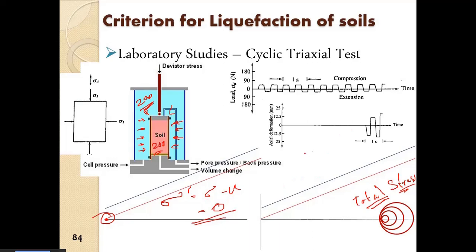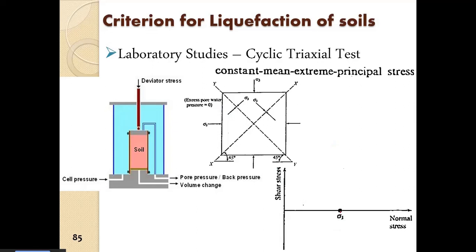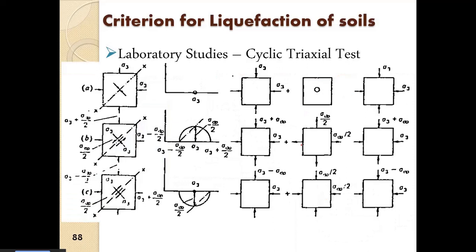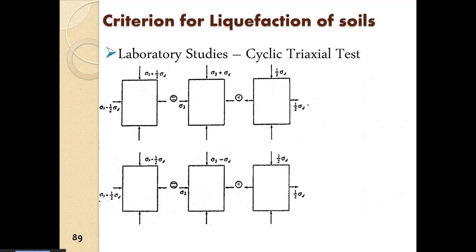So this is the liquefaction simulation in the laboratory, using the triaxial test. This is the cyclic triaxial test. Ultimately here we see that the constant mean and extreme principal stress condition was maintained in this manner.